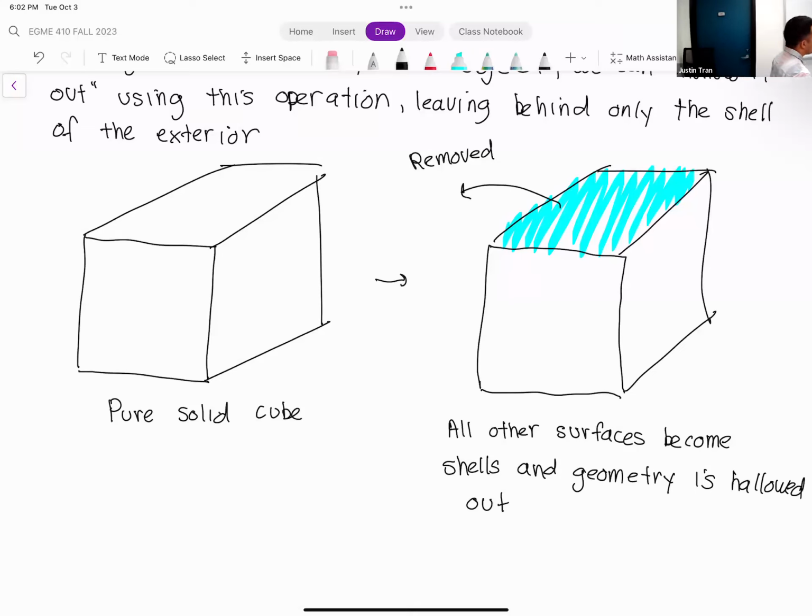And so with this operation, ANSYS doesn't have any information about the thickness. And so this would be a case where you'd have to assign the thickness manually afterwards, basically the same as activity 3, okay? But if you use a mid-surface operation, then ANSYS already knows what the thickness is, and then there's no need to assign it, okay?